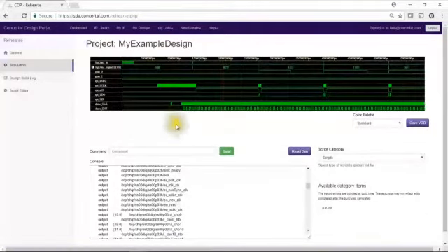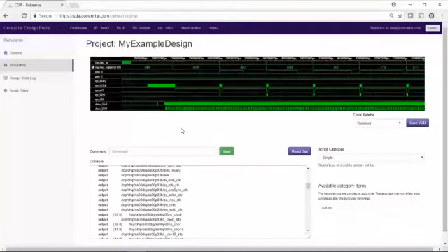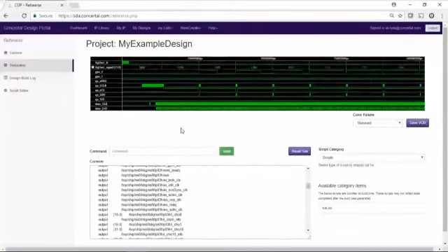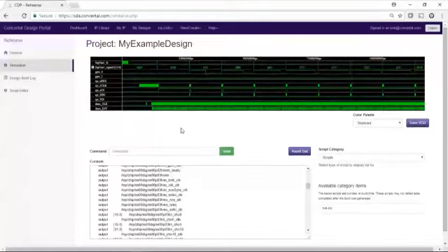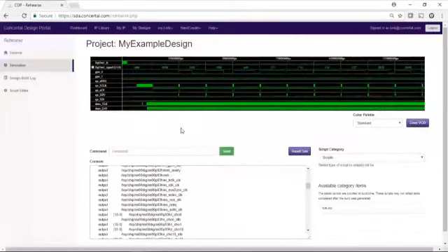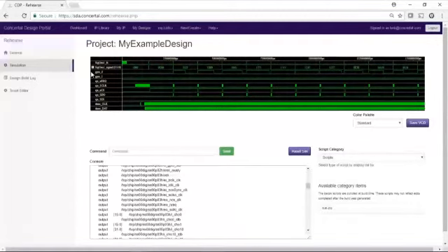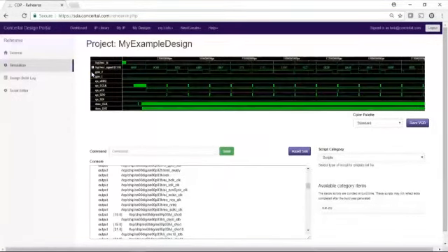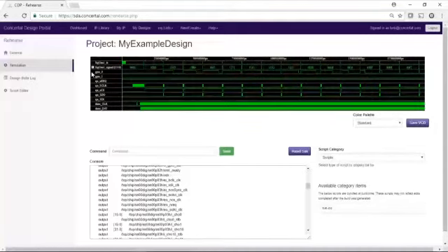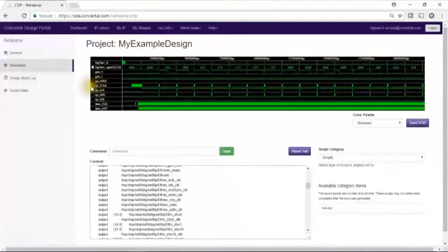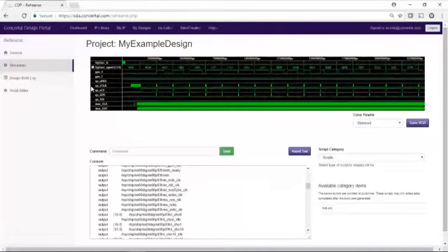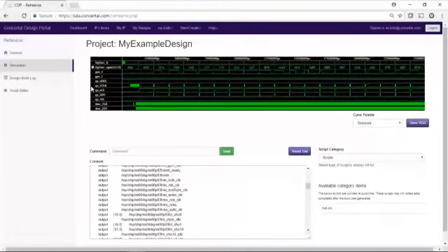The first set of signals is the on-chip signal generator, which is generating a digital sine wave with a DC offset at a specified sample rate. That output is being routed to the GPIO pin 0, which is operating as a PWM output, taking the sine wave data and creating pulse durations of the specified width. The SPI is also outputting the data, which is going over to the test bench and being received, and the test bench is routing that data to the sigma delta modulator that's providing the PDM output as a stimulus into the PDM input IP, or the digital microphone IP.